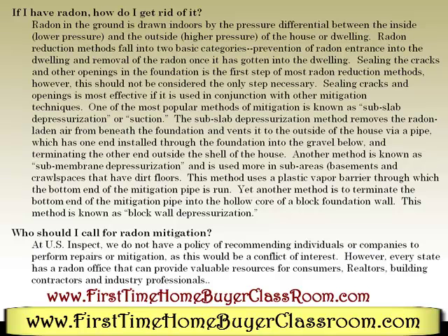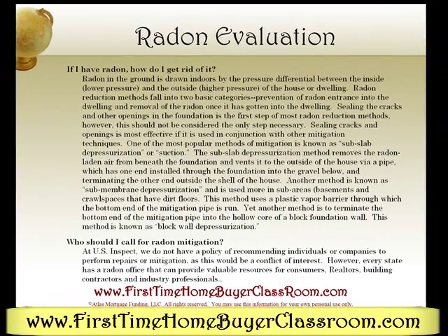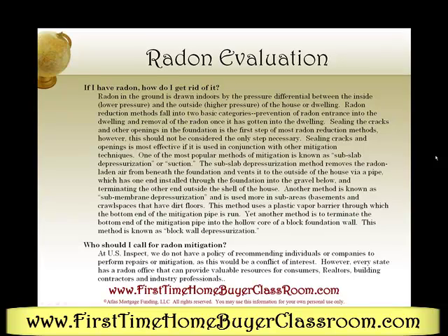Another method is known as submembrane depressurization, and it is used more in sub-areas, basements, and crawl spaces that have dirt floors. This method uses a plastic vapor barrier through which the bottom end of the mitigation pipe is run. Yet another method is to terminate the bottom end of the mitigation pipe into the hollow core of the block foundation wall. This method is also known as block wall depressurization.